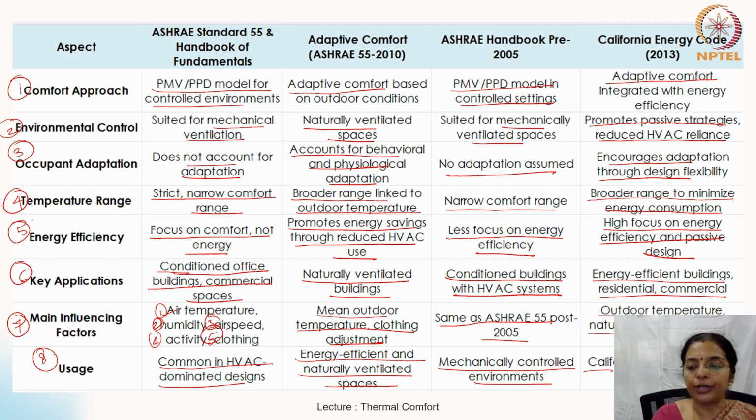So in today's class, we saw what is the meaning of thermal comfort, what does it mean to people, and what are the factors influencing thermal comfort. Do not forget what is MET, what is CLO, because all this will be useful for you when I teach you certain tools. And then we looked at various comfort models. I am looking at these 4 comfort models which are right now on your slide, because this is what is used in the tools which we will be adopting later. But you must also learn about IMAC, which is specific to the Indian conditions.